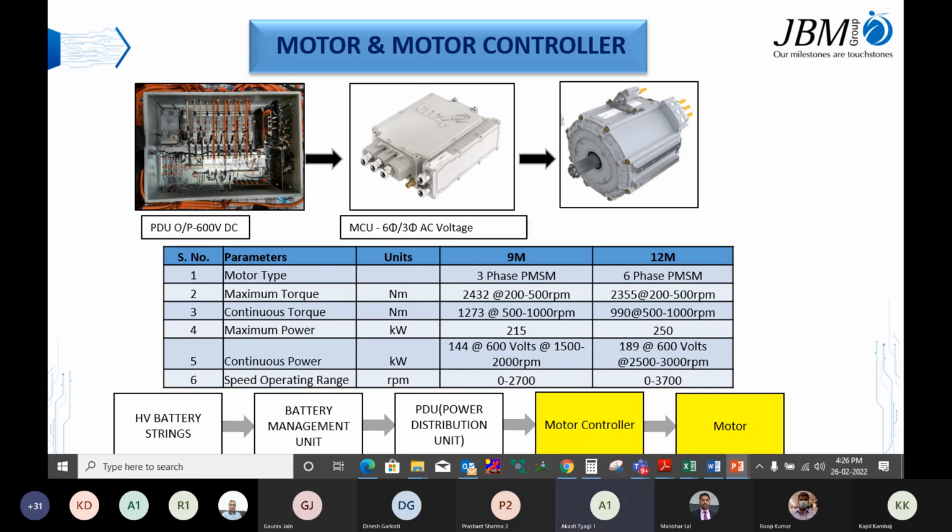Just like Kapil sir was explaining about the Lenze, that it has inbuilt memory, even MCU also has inbuilt memory, and every time there is any fault inside the traction system, MCU gets the data and saves it inside its memory. Using the Odin tool, which is provided by the supplier Dana TM4, we can access that data about the fault which is happening in the system. We track and check the data using the GDD file, which means gather diagnostics data. We take that data, we study it, and we conclude whatever the doubt is.